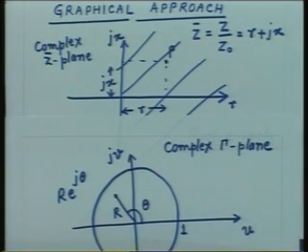So, first exercise we do is we try to map all possible impedances onto the gamma plane, and then we essentially create a graphical structure where the analysis is now carried out in the complex reflection coefficient plane.